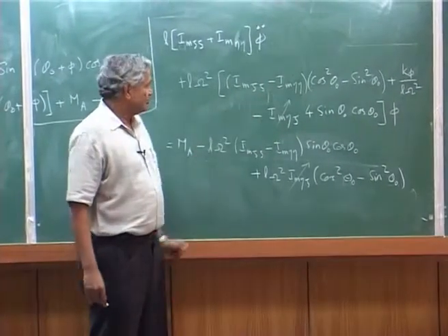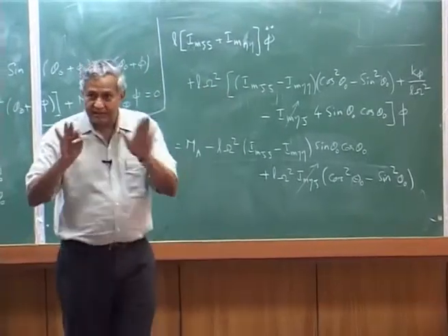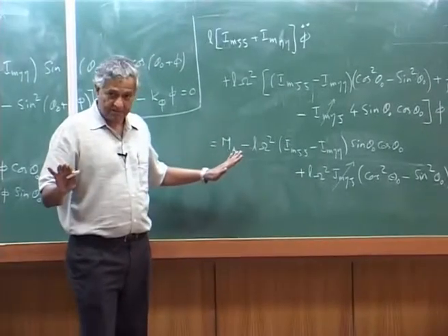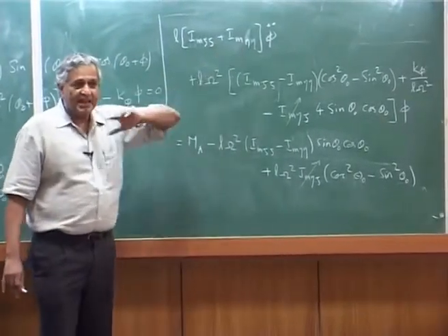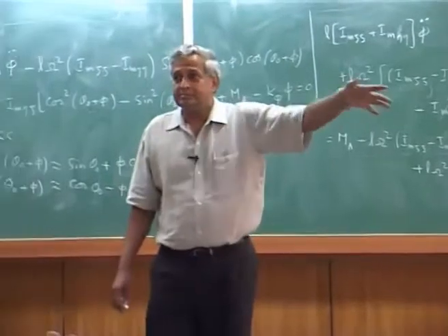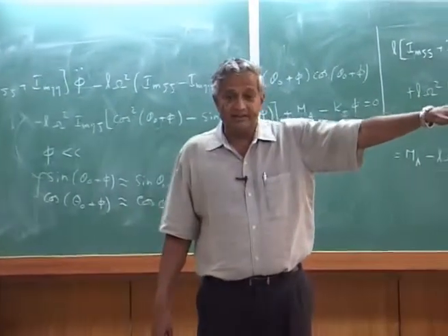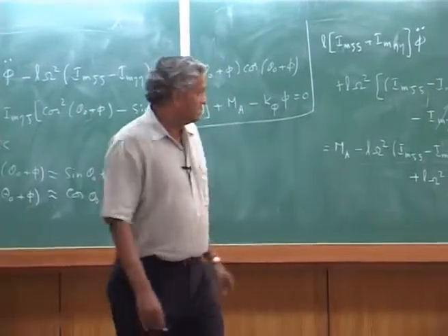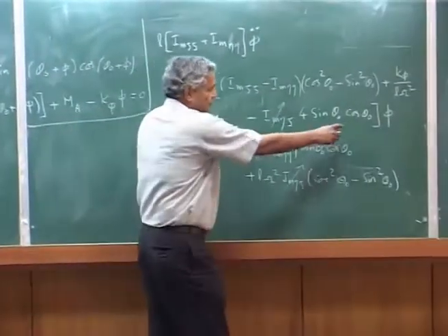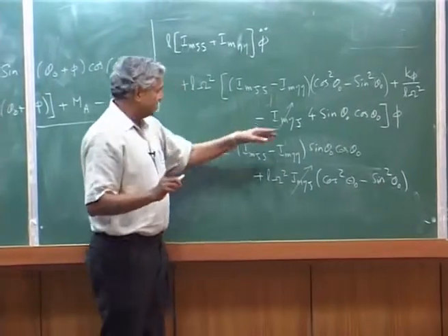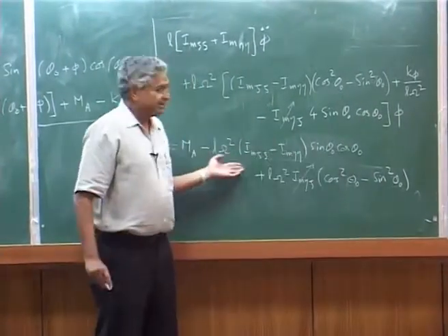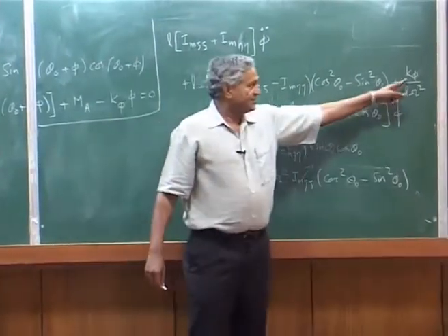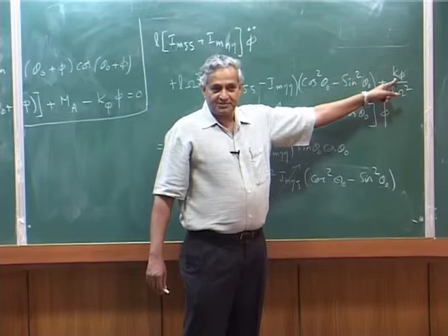Okay. You will find, without dynamics, in the sense without any external aerodynamic loads, there is no phi double dot. The equilibrium torsional deformation of the blade will be phi equilibrium equals this quantity divided by this quantity, and that depends on what is the torsional stiffness.